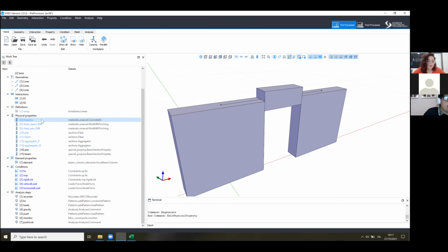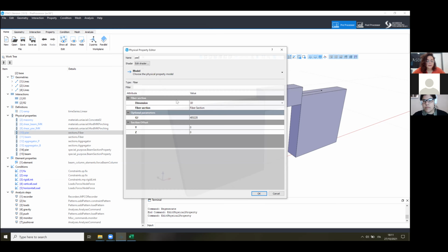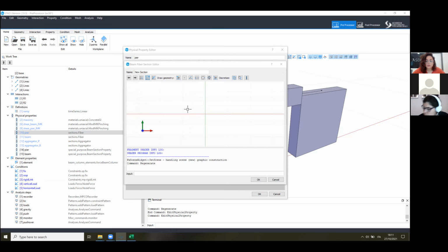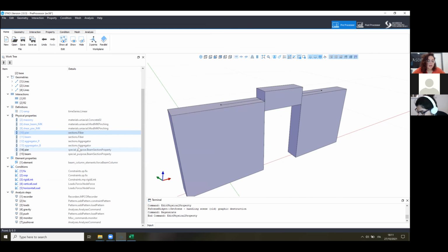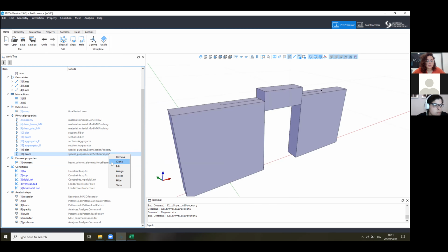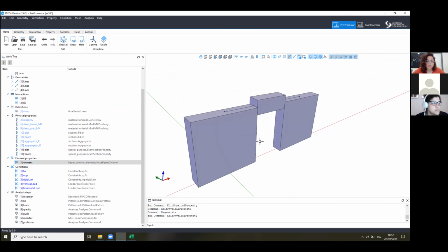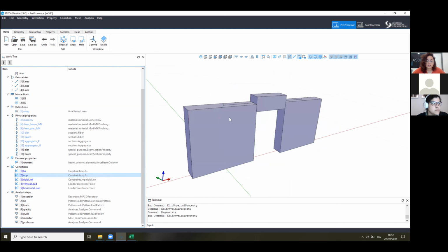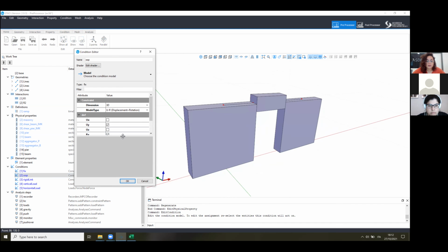Then going forward, not talking for a second about the shear, we define fiber sections for both the pier and the beam. And we include them in an integration scheme with 5 integration points for the pier and 2 integration points for the beam, because the beam element is quite small and we don't need so many integration points along it. And to both, we apply a force-based beam column element. So this kind of setup can be just fixed at the base. We fix the model in the out-of-plane direction. This is a suggestion that I give you every time you're trying to do a 2D model in OpenSees and STKO, especially if you're doing a 3D frame structure and not a shell.